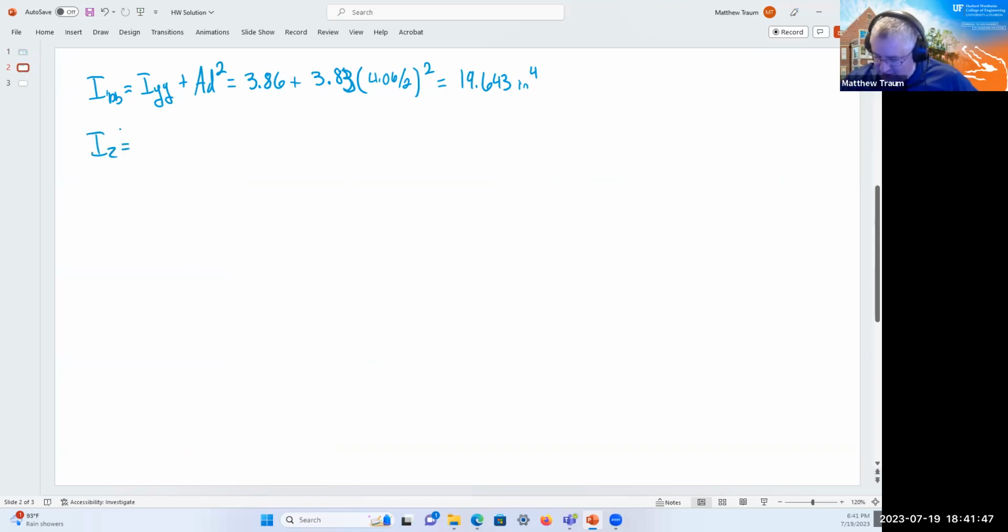So IZ is just equal to 2 IBB, and that works out to be 39.286 inches to the 4th. So doing pretty good here.